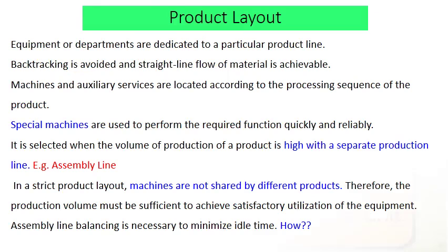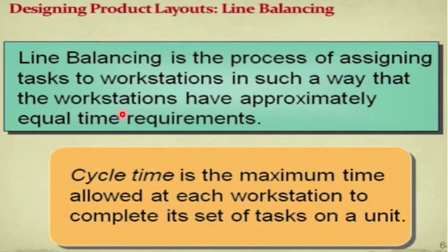Let us see some designing of product layout. That is, line balancing is the process of assigning tasks to workstations. There are different workstations and overall equipment in such a way that the workstations have approximately equal time requirements.